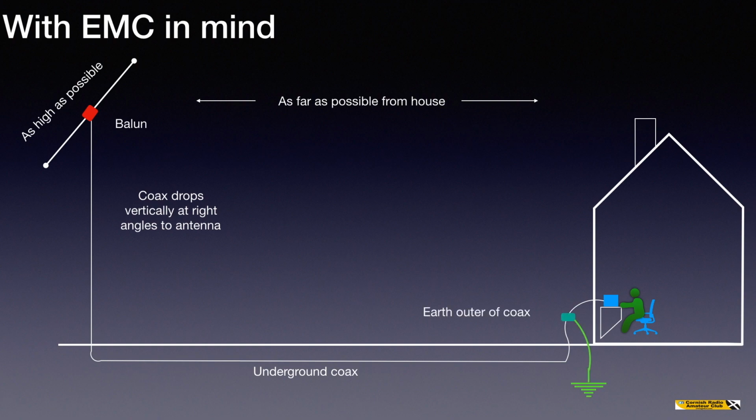And most importantly, there is an earth stake for RF earth only. And I would urge you to look at the Foundation Now book so that you clearly understand the difference between the shack earth, the RF earth, and the mains earth, and the different functions of the two earths.